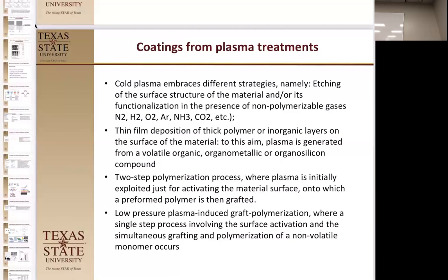If you react it with oxygen, you get hydroxyls on the surface, or amines or nitrogens, or you can even do halogenated materials as well. So then you've prepped the material for the inorganic material, and then you can actually plasma in things that generate inorganic materials directly, either from organometallic volatiles or organometallic involatiles that you've already infused in your system. And then that can start to react with the surface as you plasma.